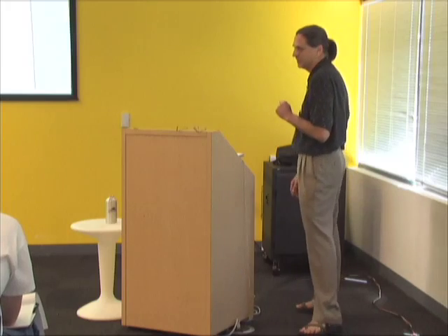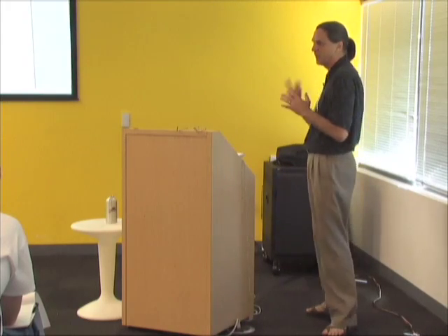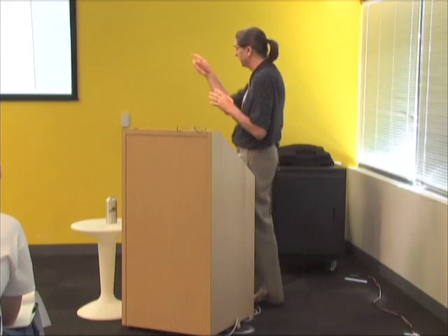Before you open a large model, make sure you go through and change your dialog boxes, change the component to list view, close the outliner, close the layer box, close the component dialog, because all those things populate when you open the model up. So you're going to sit there and wait every time. One of the things that was happening when I was switching models is that I had the outliner open, so it's regenerating the outliner when it comes up. Turn off shadows.